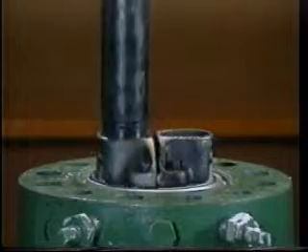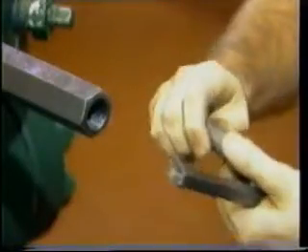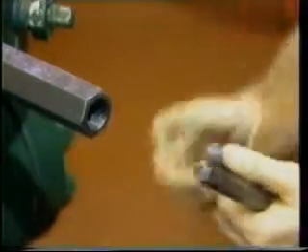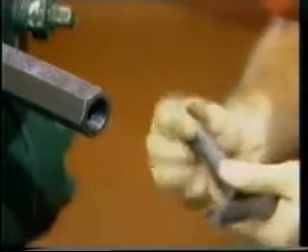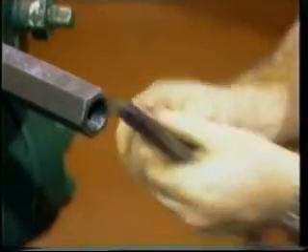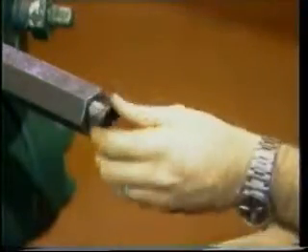The tubing strings and casing annulus are sealed off by energizing the seals by injecting plastic packing into the injection ports in the tubing spool. To provide additional protection against leakage, a seal pad above the tubing hangers can be energized by injecting plastic into the injection ports in the master valve flange.